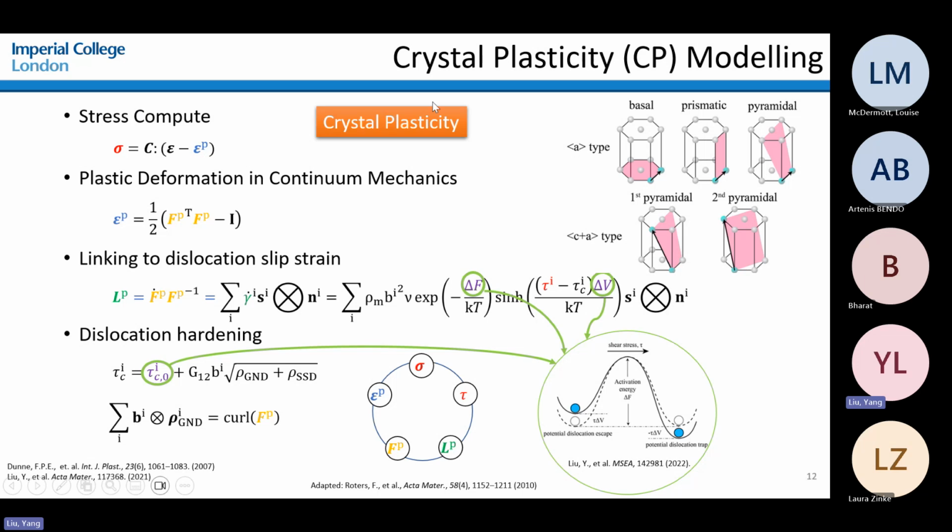And the crystal plasticity would be able to describe each of the components in these slip systems to accommodate the plastic deformation at the crystal level. And also we have parameters to understand the behavior of the material strength as well as the rate sensitivity of the material, which is basically, during a long stress holding period, you would expect the material to be changing with time, which is rate dependent.